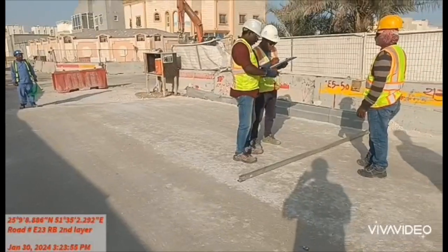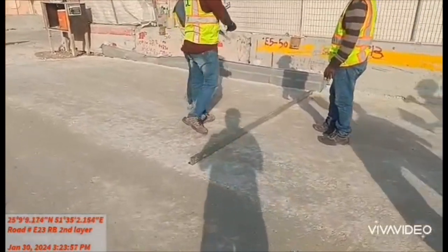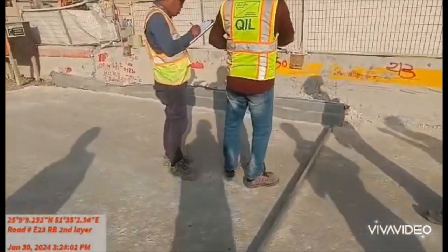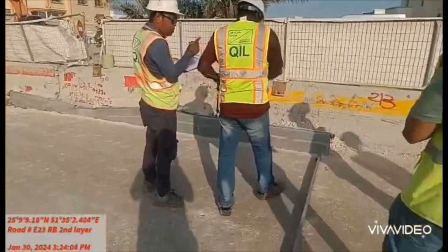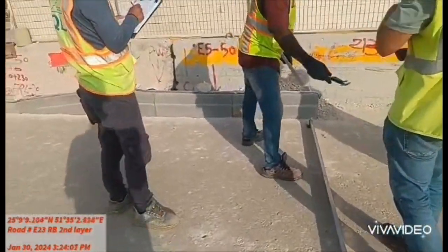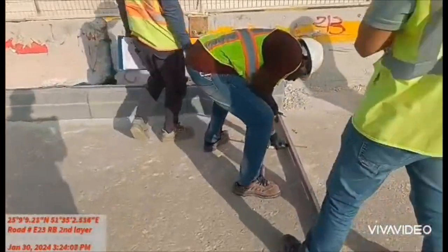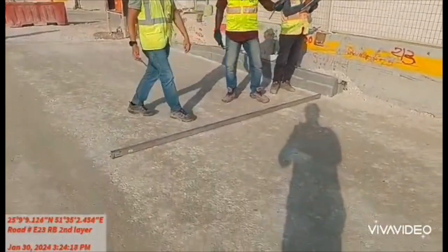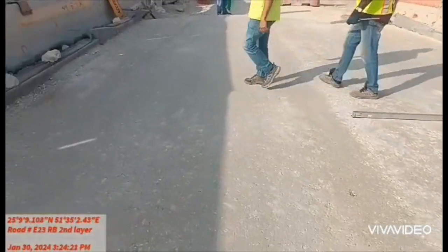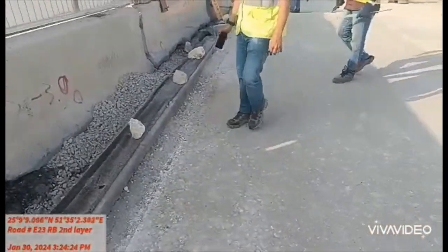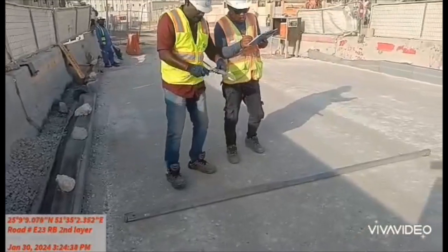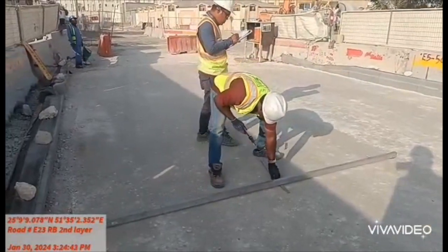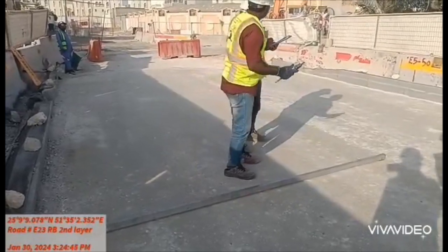Now the compaction test is almost completed, and another test is now ongoing here, which is called Evenness. The evenness of the road should be checked on the road base top level, and this should not be more than 10 mm plus or minus. If any point is more than this, it is to be rectified as per the required specification, and the test interval should be 20 meters each. For the subgrade we are conducting at 50 meters, but for the road base it should be conducted every 20 meters.